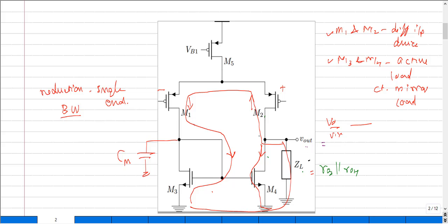We know that when there is a DC current that flows across this node, which I labeled as I0, what I have across the drain of M1 and M2 is basically I0 by 2. And this current, when it flows through the diode-connected transistor, creates a VGS3. The value across this node is just VGS3.